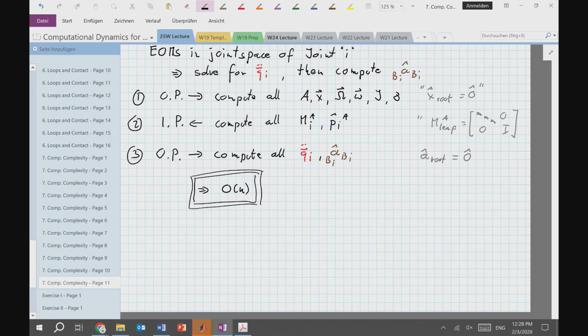Still blows my mind. Right? Everything we learn, the equations that we derive, the equations that look pretty, they are all order n cube. And then someone comes along, Roy Featherstone, by the way, that's the someone, who figures out that if you do this joint by joint, if you do it in a smart way, if you think about these quantities, these projection methods, these mass matrices in a bit of a broader way, you can do this in order n time.